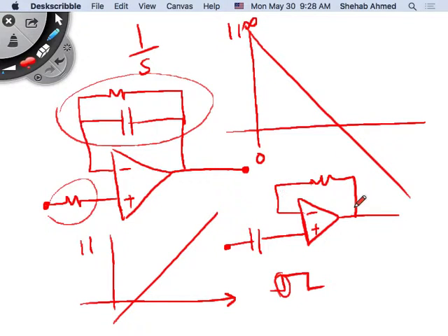What is this circuit going to do to high frequency content? Amplify it significantly, right? So do we want to do that? If you put a signal through a differentiator like this, for example a signal that looks like this, something that has some sudden rises, what is this amplifier going to do? Anytime it sees high frequencies, the gain will be infinite, right? So you will have huge spikes in the output because the gain is infinite at that point, right? So how did we solve this?